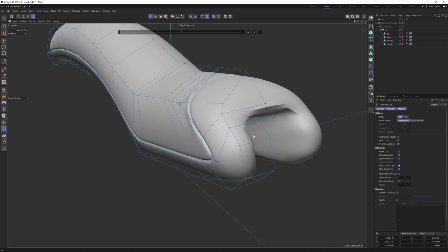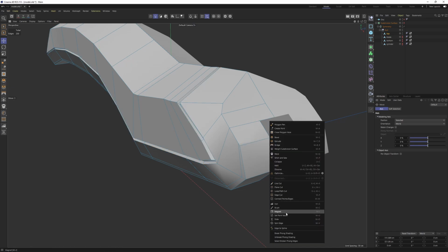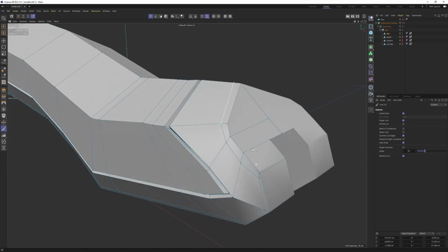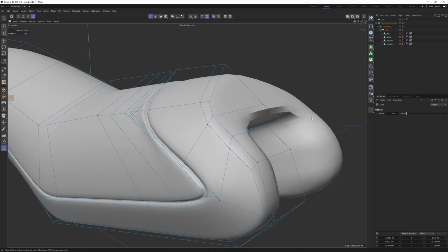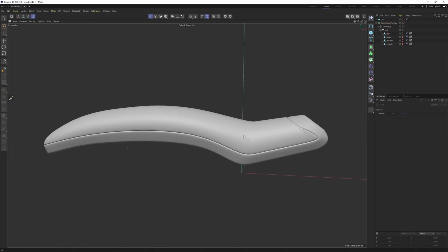but I don't want that edge. So let's see what we can do. I can make a loop selection, then deselect that one. Up to that point, I can move on with line cuts. Then points mode, slide tool, press Ctrl and slide. Let's press Q. Okay, not bad. It's coming together.